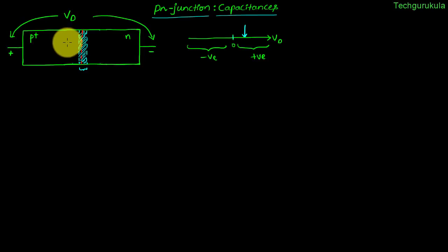When we forward bias, what happens in terms of current components is that the majority carriers, holes on P side, would get injected onto the N side. And once they go there, they're basically minority carriers in the N side. And deep into the N side, the carrier concentration of minority carriers would be very small. As a result, there is a concentration gradient of the holes in N side. So the holes would diffuse deep into the N side. When they do so, they recombine with the majority carriers, electrons, and the concentration of injected holes would decrease as they go deep into the N side.